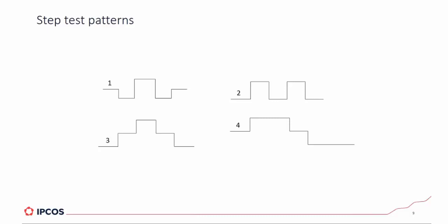The staircase pattern, as we see there, number three, is typically applicable when we want to find a certain nonlinearity. For example, we want some data of a valve constraint, where we are typically operating at, let's say, 50%, but we would also want some data around 100% and be able to transform that input by using the data.